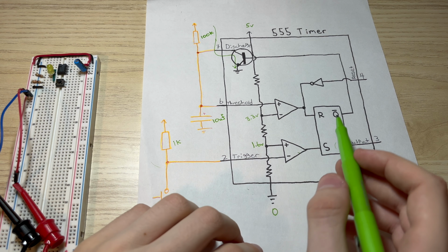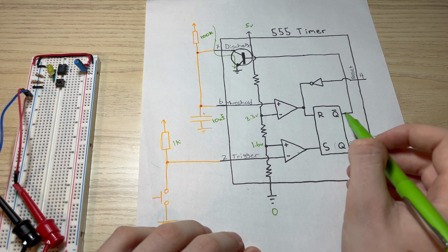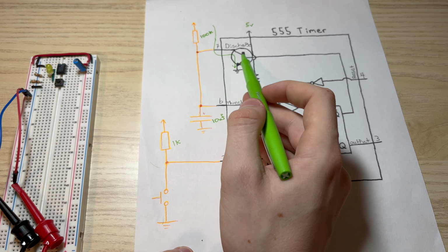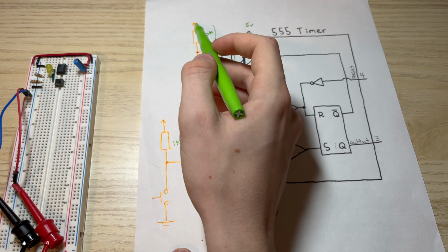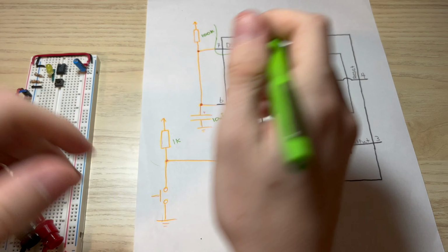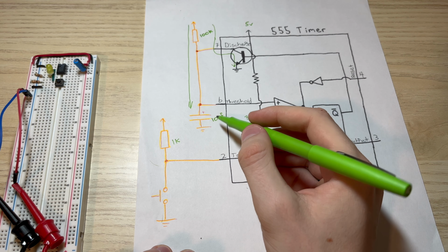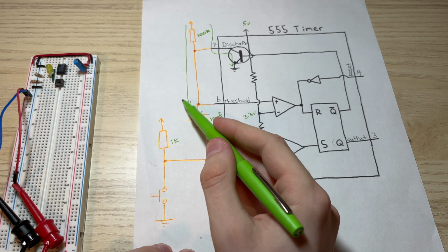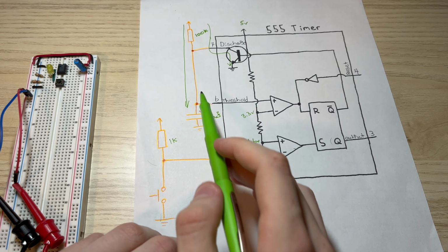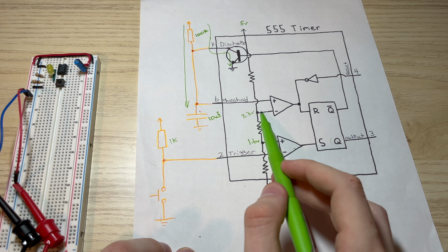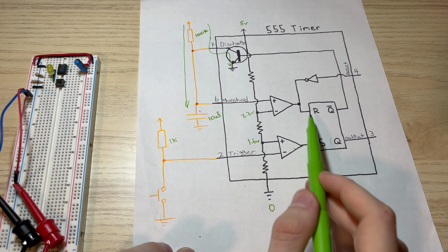Now what keeps that output on? Well, now we turn this transistor off, so current is not flowing through this transistor anymore. The only way for it to flow is down here, so current is flowing into this capacitor. Now this capacitor is charging up. And by the way, before this capacitor starts charging up, it was at 0 volts, which is less than 3.3, so this was off too. Everything was off in the default state.